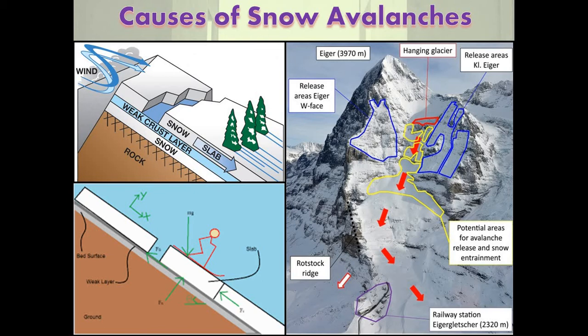However, the loading rate is critical. Heavy snowfall over a short duration leads to a greater probability of avalanche occurrence. Snowfall of 1 m in one day is more hazardous than 1 meter over 3 days. When the snowpack becomes unstable, it is released suddenly and descends rapidly down the slope, either over a wide area or concentrated in an avalanche track.